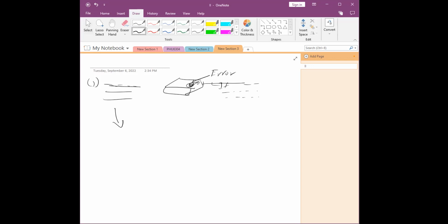The easiest way to convert your textual description into a mathematical form is by using truth tables. Because in the truth table, you can say, okay, A, B, and C are the sensors. When sensor A is on and sensor B is off, indicate this light. When sensor B is off and sensor C is also off, then indicate like this. So like that, you can fill the truth table. That's very easy.